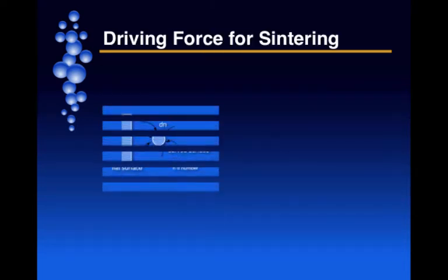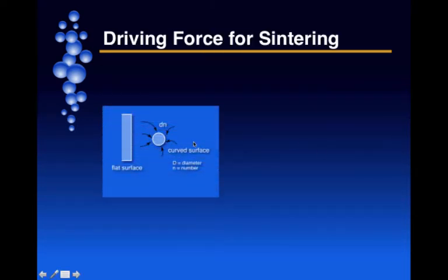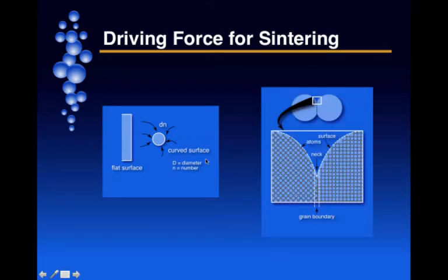In terms of the driving force of sintering, we've seen that the presence of a curved surface provides a stress. A flat surface does not have that. Think of a balloon filled with air, right? That surface is under pressure. And another way to look at the surface is, you can see over here two particles, and let's take a magnified region represented by the atoms.